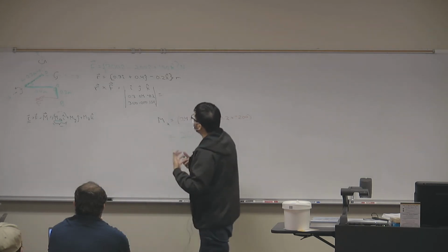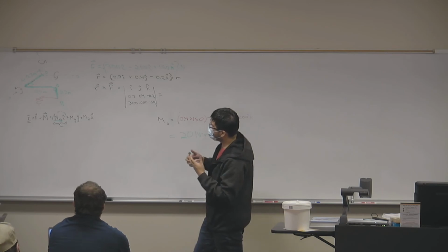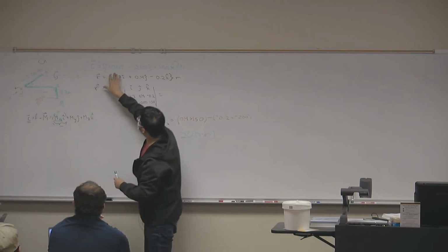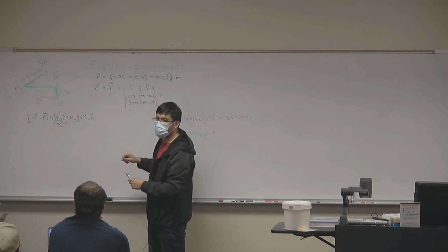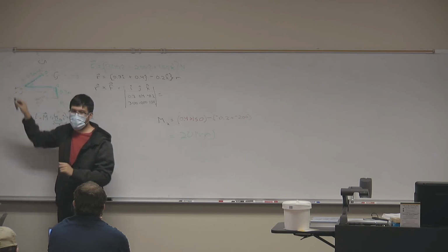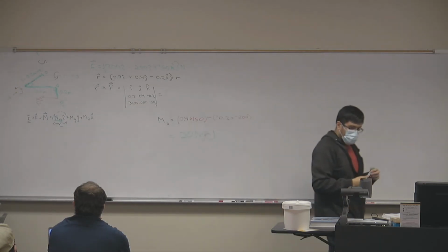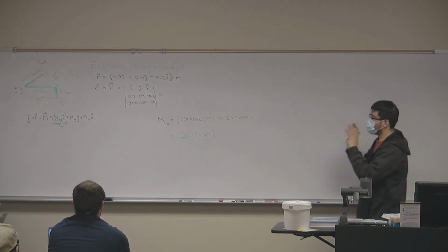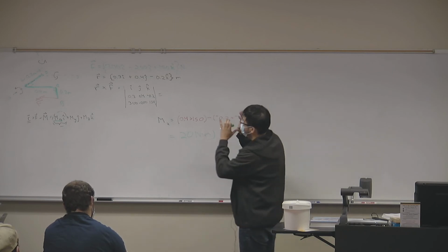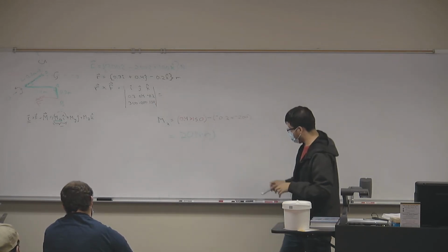You may be a little bit confused because if you look at this, it kind of seems like this force is coming underneath it, but focus on the components. If you look at these components, then you see that the force actually passes a little bit above the x-axis. So try to look at things in terms of vectors, not so much graphically. When you look at the graph, it can be tricky. So try to look at your vectors, your components, in order to understand your signs and your orientations.